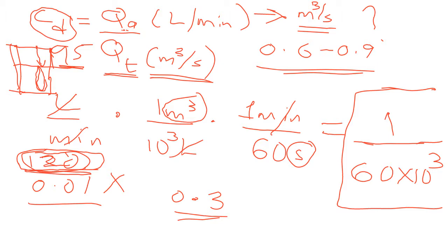And then, one question I normally ask you is, okay, let's say you got the coefficient of discharge to be 0.8. Discuss, comment on the value. Simple comment on the value, because the coefficient of discharge is actual flow rate over the theoretical flow rate. So it's more or less like an efficiency of the hydraulic structure. Because the closer it is to 1, the better.